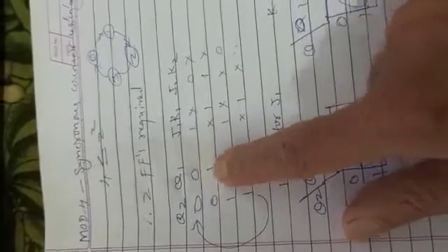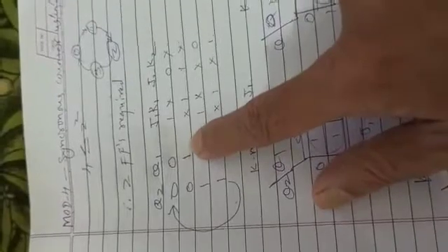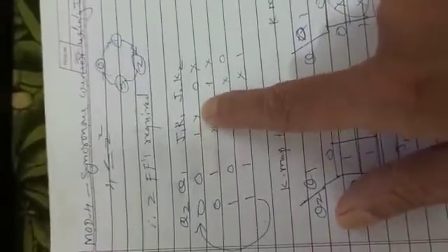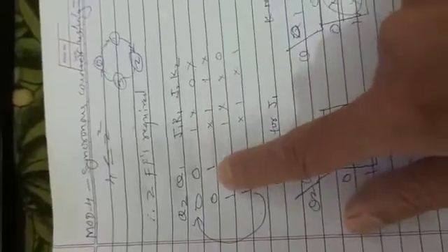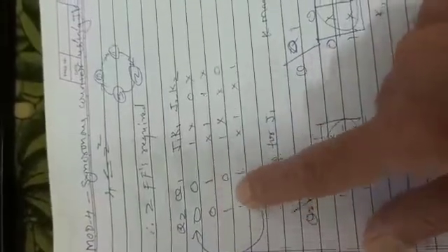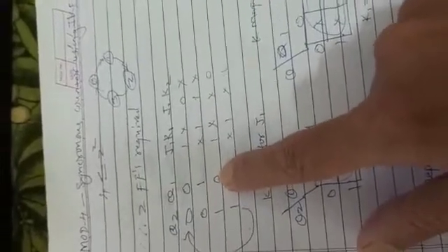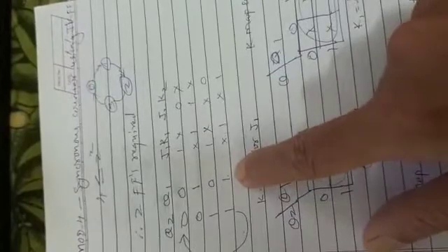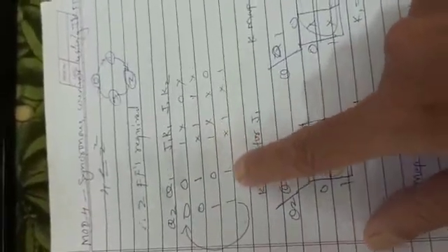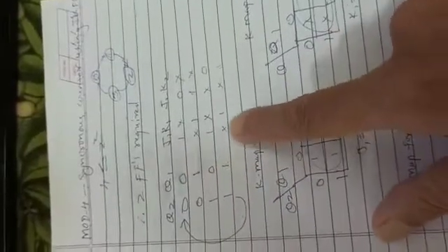Okay, now if you observe here, while going from this state to this state, Q1 has to go from 0 to 1. So what input do you have to give from the excitation table? While going from 0 to 1, the input required for flip-flop 1 is 1x. Okay, this is from the excitation table. Then next, while going from this state to this state, Q1 again has to change from 1 to 0. That's why the input required is x1. This is also from the excitation table. Then next it has to go from 0 to 1, so 1x is the input, and then it has to go from 1 to 0, so the input is x1.